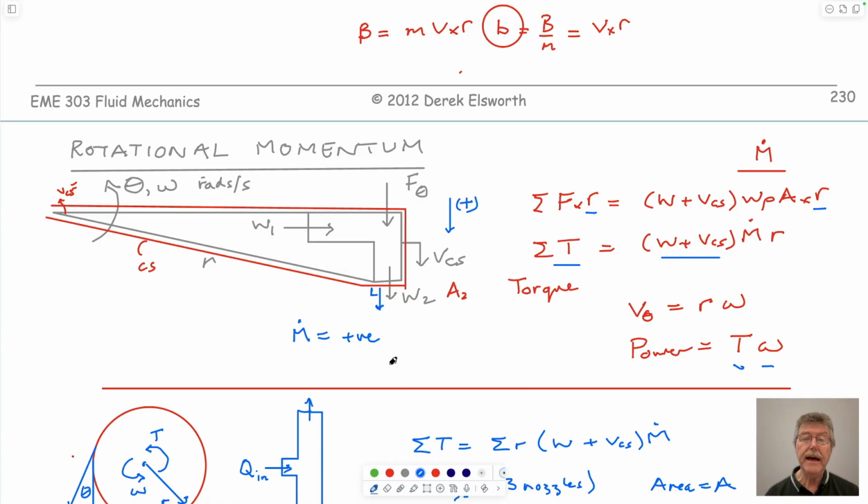And you could imagine also, when we talked about the vane, and you can rationalize this, if you're feeding water in at some static velocity from a hose, the maximum velocity, if this has no force acting on it, if F is equal to 0, will be what? It has to be that this bead of water is just hitting the surface, and the surface is moving away from it.